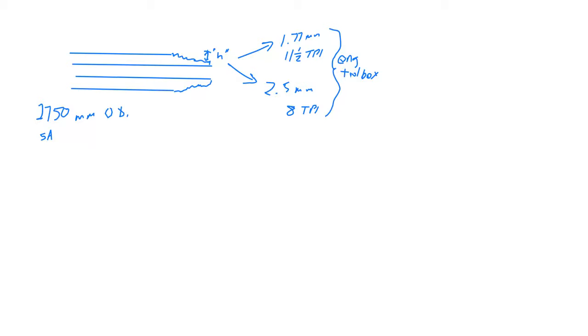It's SA 285, grade C, and it's got a MOP is 2070 kPa, and the mean temperature is not to exceed 250 degrees Celsius. So that probably is the saturation temperature of the water plus a few degrees. The joint is welded and all joints have an efficiency of 1. And it says, what's the minimum thickness?